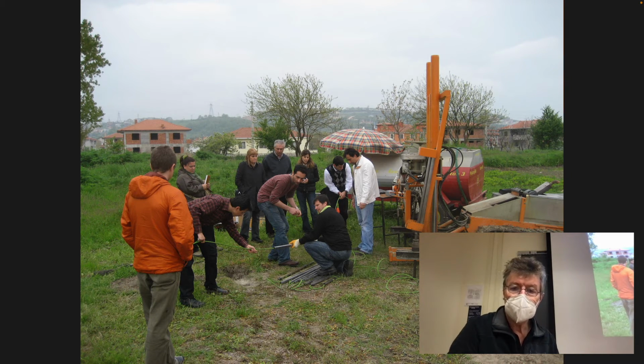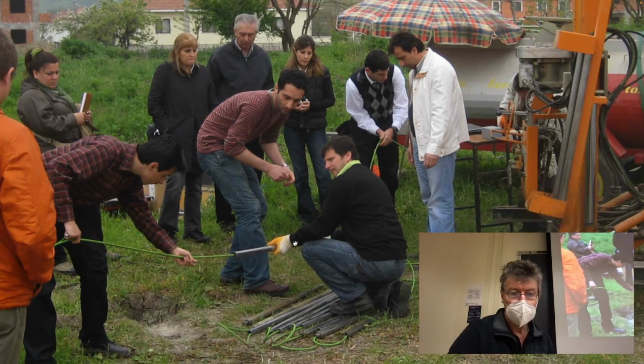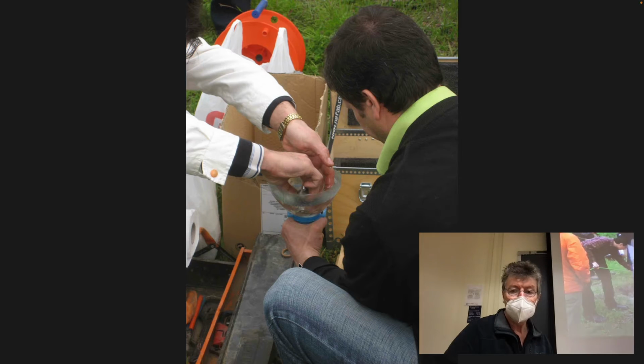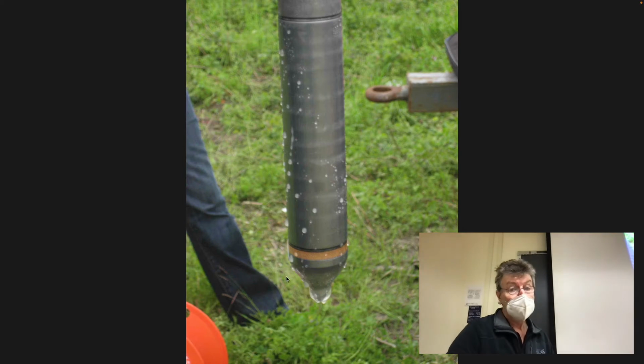So this is the idea. You have this little gantry here. You have a crosshead that is able to take these pieces of drill tube. They're probably a meter long. They're hollow. The data cable gets passed along the interior lengths of these tubes, and then they're used to physically push this conical probe. So you can guess this is to saturate. This is a porous element at the tip.